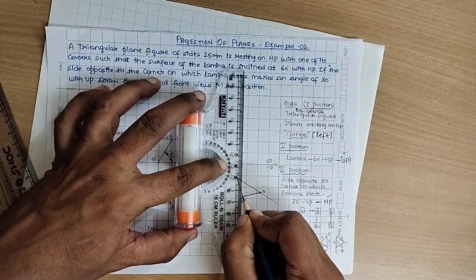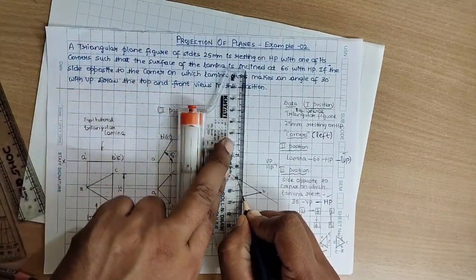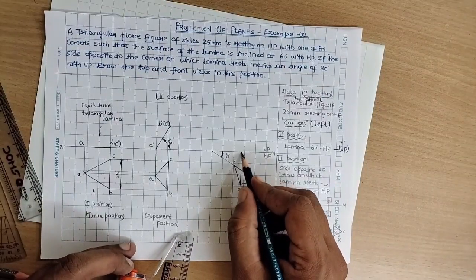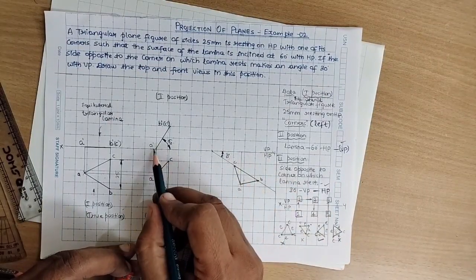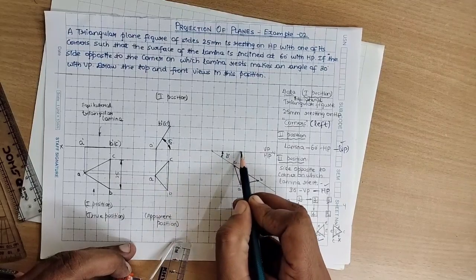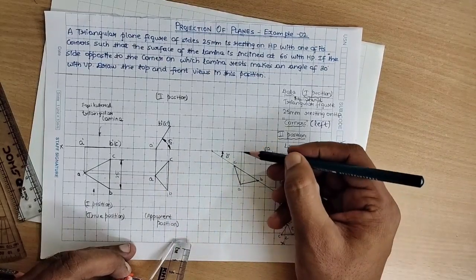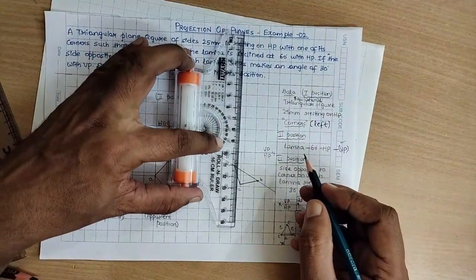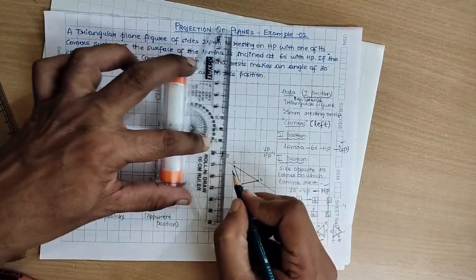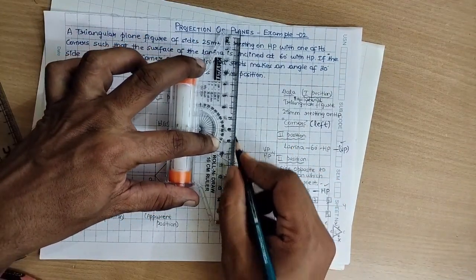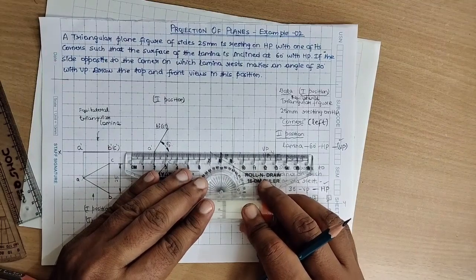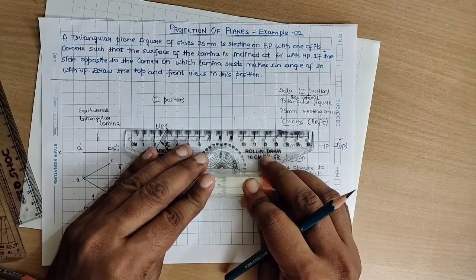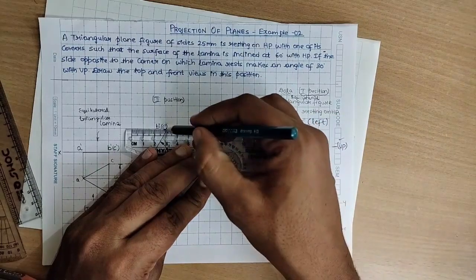Drop a perpendicular from the point A. I will stop this vertical projection, the projection line, at the XY line itself. For the reason, if I have drawn from this end, both will intersect at this point. So no need of extending the projection line till the other end. Similarly, projection from the point B and the projection from the point C. Draw the horizontal projection from point A. It's not required as I mentioned. It is on the XY line. Draw the projection line from B and C.